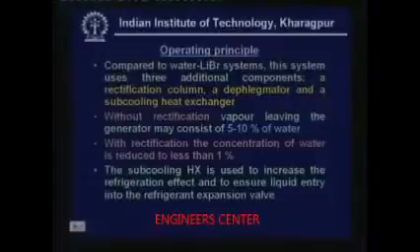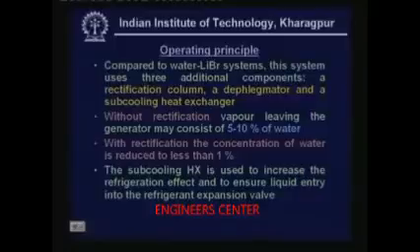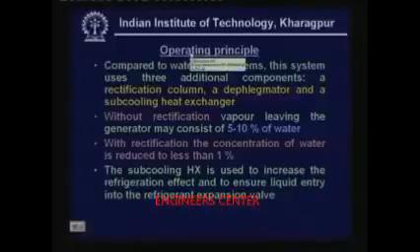Okay, and what is the function of subcooling heat exchanger? The subcooling heat exchanger is used to increase the refrigeration effect and also to ensure that only liquid enters into the refrigerant expansion valve. Now, let me explain the operating principle.